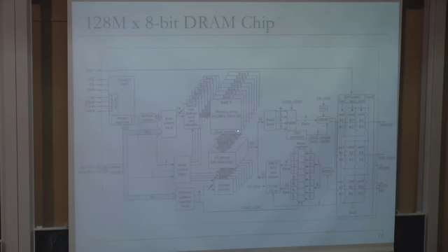And these are the sense amplifiers for each bank. And you have the column decoder that selects the data from the sense amplifiers and sends it out of the DRAM chip. And there is a bunch of circuitry to ensure reads and writes happen nicely in DRAM. But we will not go into that. But this is the basic microarchitectural structure.